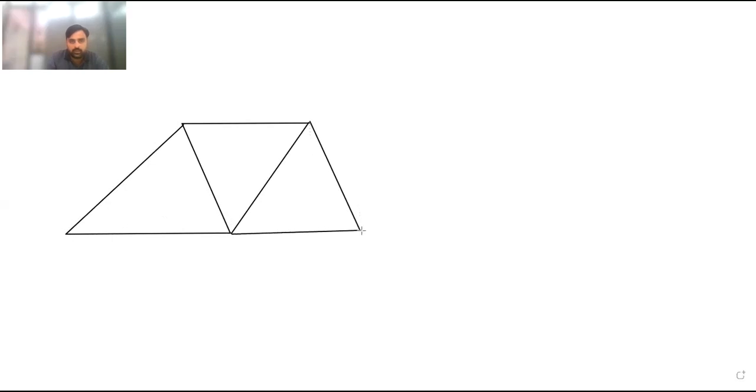Okay, so this is the given truss which we are solving. It is symmetrical. Reactions I will draw now. Here, hinge support is given at this point, so there are two reactions, VA and HA. And at the second point, RD, roller support is there.